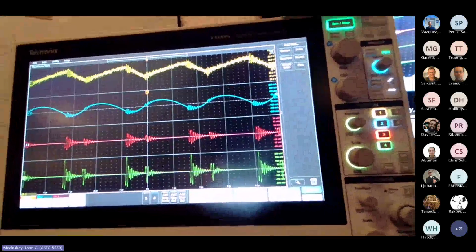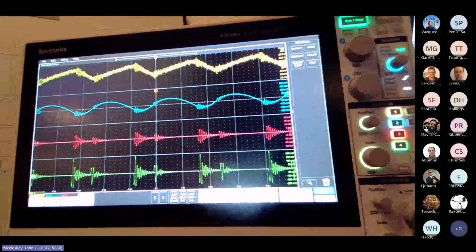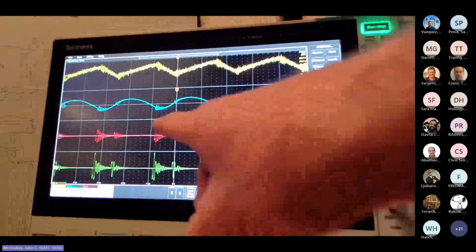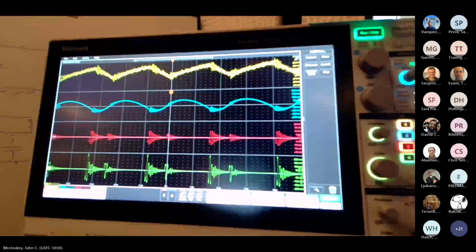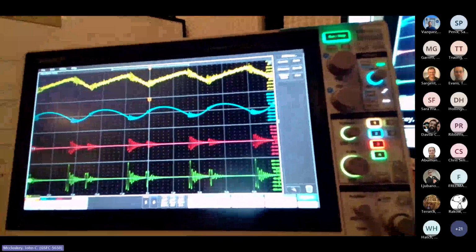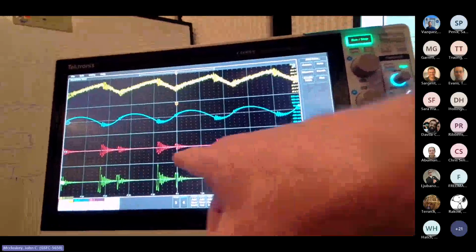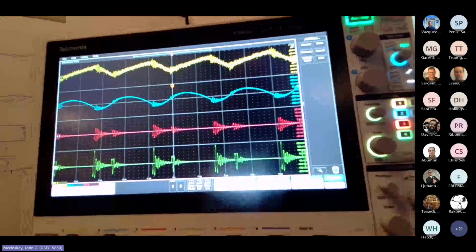Especially if a coupling or crosstalk problem might be much more of a time domain problem, right? Like you've got a digital system and you've got all this kind of junk going on, but it's away from clock edges, so you never see it. But in an issue I was helping with just a couple weeks ago, we had this kind of stuff walking across a serial data transmission.